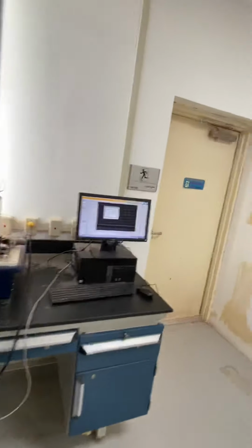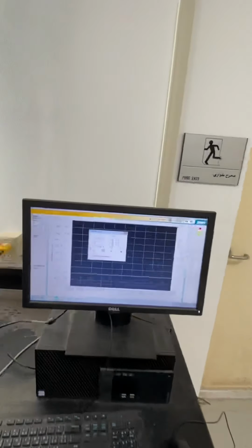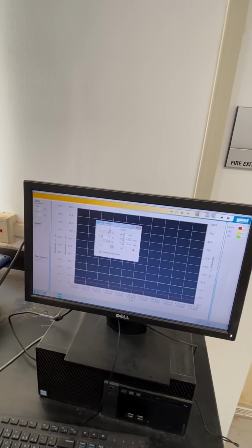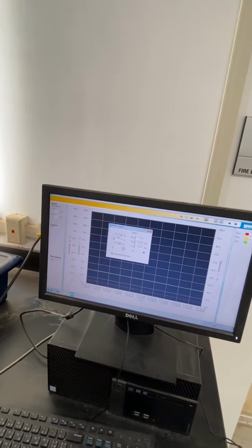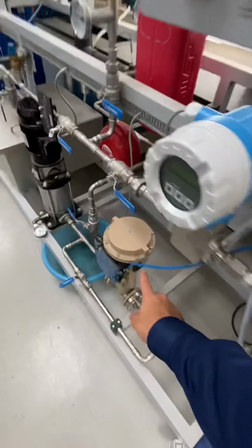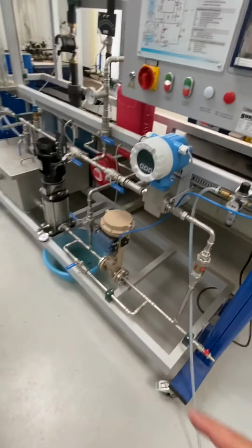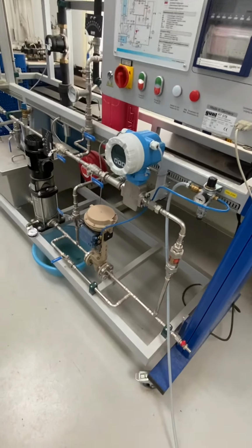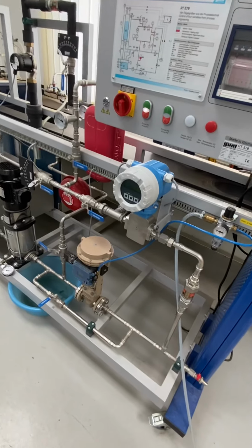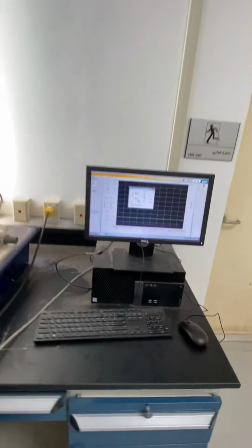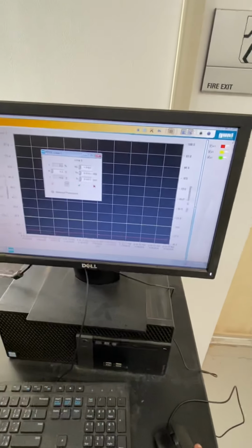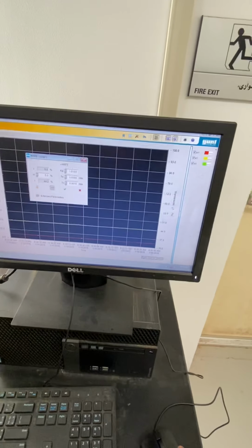The controller will calculate the error, and once it finds that there is a positive error, meaning that the process value is above the set point, it will try to bring the process value back again to the set point by closing the valve, the automatic valve. Remember that the controller is connected to the automatic control valve, so the output signal will decrease, telling the control valve to close in order to bring back the process value to the original set point. So with the help of the trend, we will see, guys, that this is what's going to happen.